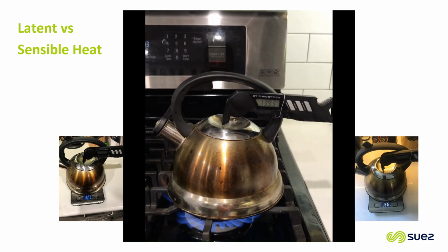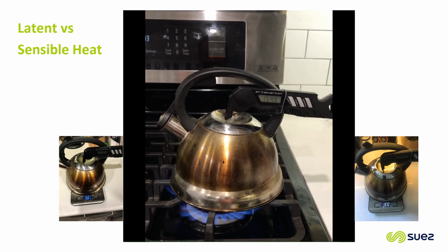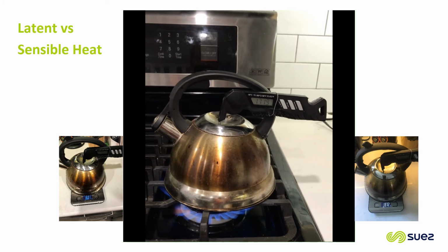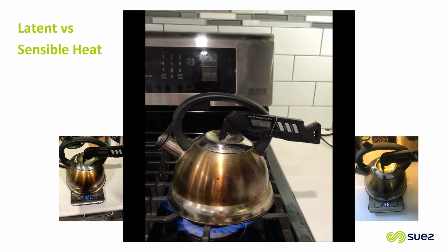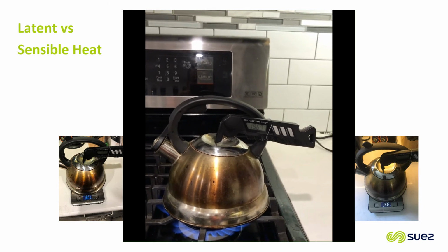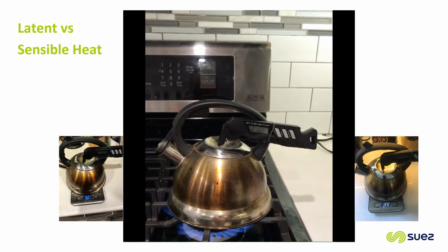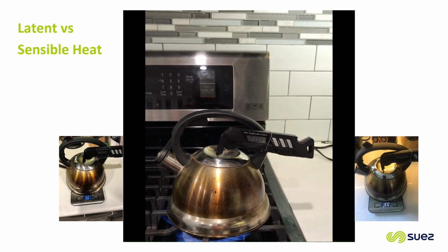Going to capture these numbers in a minute to do the calculation that tells us how much heat is being added and the difference between latent and sensible heat. Right now we're obviously still adding sensible heat. And now we can hear the production of steam, which says that we are adding latent heat.